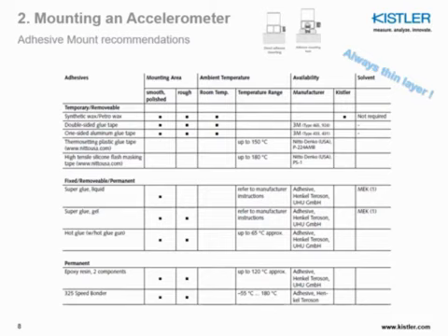Then it could be an adhesive mounting base used because, first of all, you don't want to have any damage to your sensor base if you need to scratch off the adhesive. And second of all, it's usually the case for people that want ground isolation. In that case, those bases are made of aluminum.